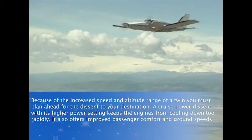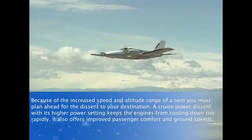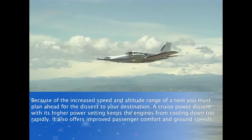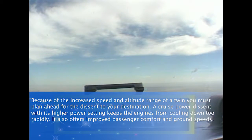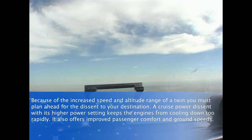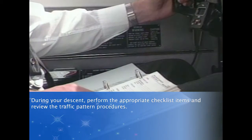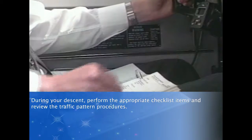Because of the increased speed and altitude range of a twin, you must plan ahead for the descent to your destination. A cruise power descent with its higher power setting keeps the engines from cooling down too rapidly. It also offers improved passenger comfort and ground speeds. During your descent, perform the appropriate checklist items and review the traffic pattern procedures.